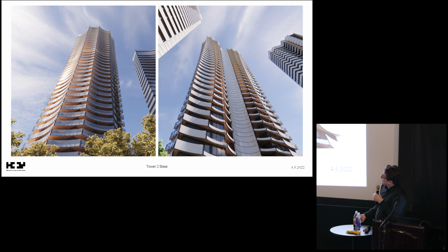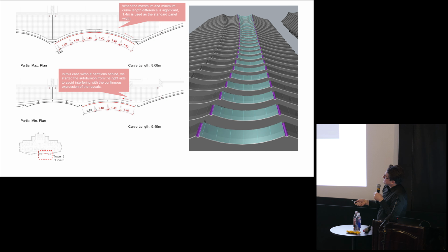This is trying to define the face and produce that curvature with very, very subtle adjustments in the edge of slab. Right? If you scooch out by 6 inches on every floor, you can produce that bow in elevation, which produces that sculptural quality. So these are the kind of drawings we're doing. We're trying, in this case, to hold this gap and then curve that one just by modifying the edge of slab.